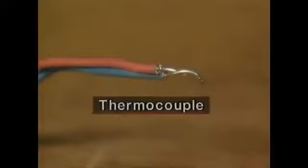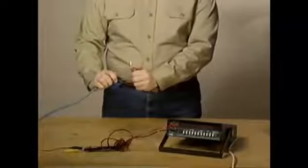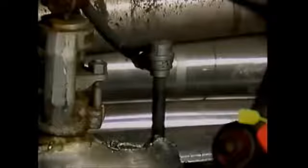Another source of electrical potential is heat. One device that uses this source is a thermocouple. A thermocouple basically consists of two dissimilar metals that are joined together. When heat is applied to a thermocouple, the electrons in the metals move in such a way that an electrical potential develops. If the thermocouple is connected as part of a complete flow path, current flow will result, as indicated on this meter. As more heat is applied, the electrical potential and the resulting current flow increase. Since the amount of heat applied to a thermocouple is related to electrical potential, and therefore to current, thermocouples are most often used as temperature sensors in process systems.